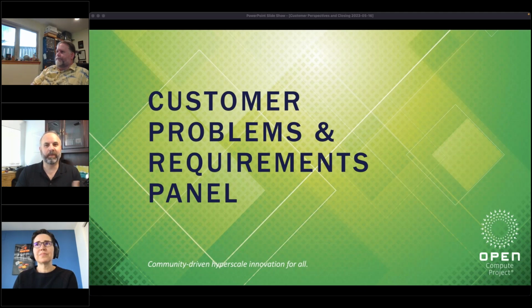One thing I might add real quick is, I think one of the differences between the SAS and SATA spec and the NVMe spec is the specs that we base them off of in the industry. SAS and SATA are pretty mature. There's not a huge amount of changes going there. So it's really trying to get that consolidation and getting all the features we need from the specs that exist. For the NVMe spec, we probably don't know what we don't know yet, and that's really going to be the future stuff that we put in. NVMe is a very dynamic spec itself. As it adds new things that are optional, we want to call those out in our data center NVMe spec, especially when they're optional, because then we want to specify whether we need them mandatory in our spec.